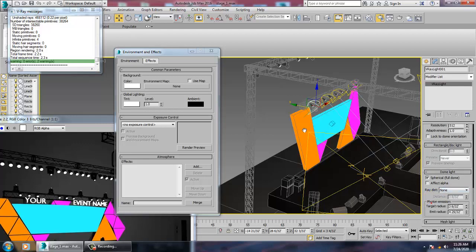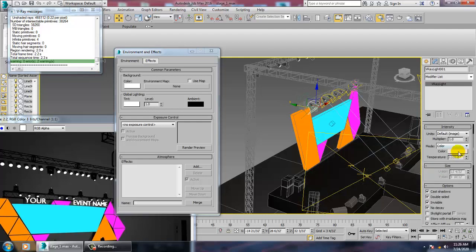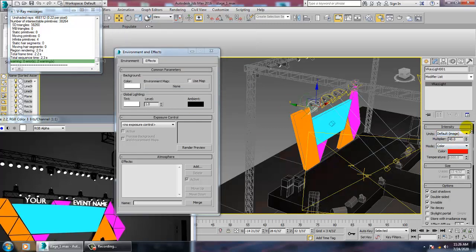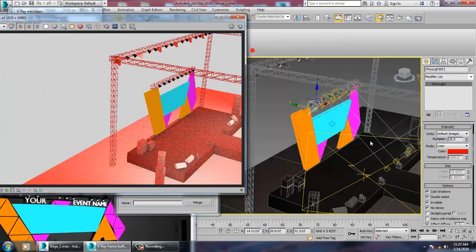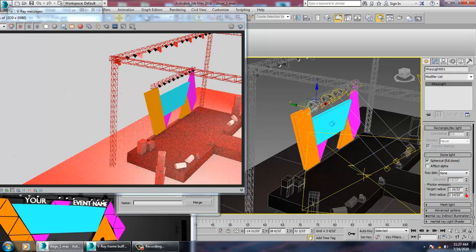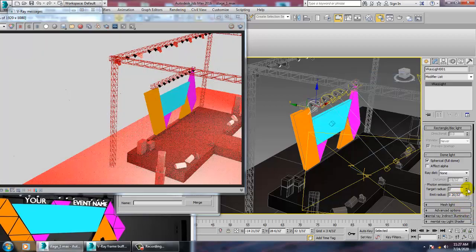So you can reduce this target distance of the light, emit radius. So it's like, for example, give a color to the light, and if you increase its intensity and now render it, you see that it's emitting the maximum area. We can reduce that emit radius. If you reduce this emit radius, it will definitely reduce this.